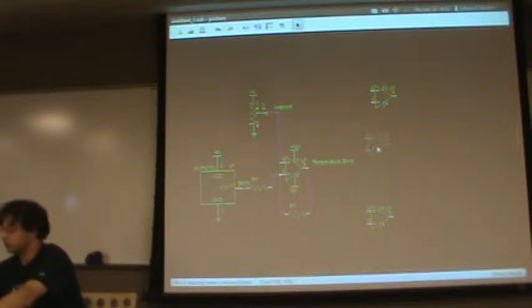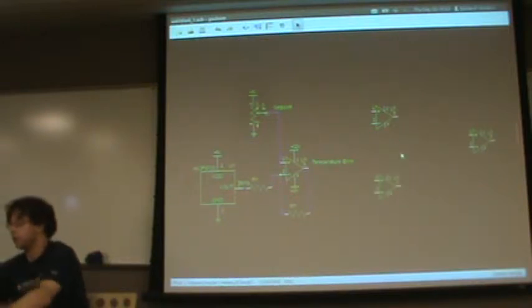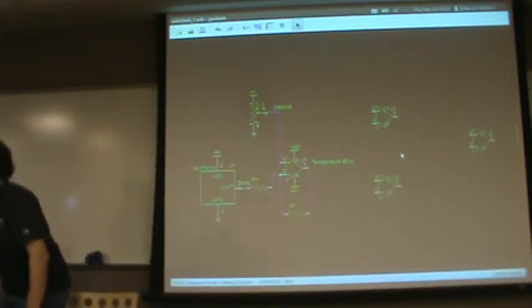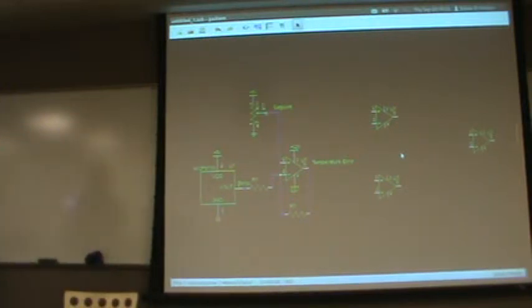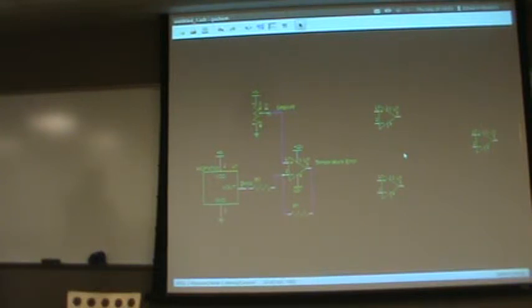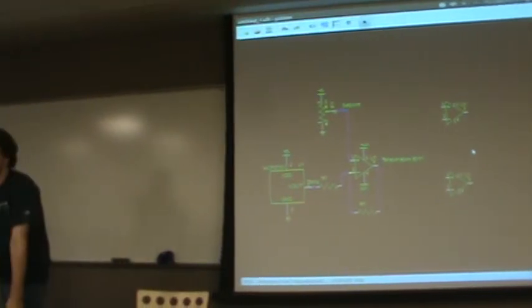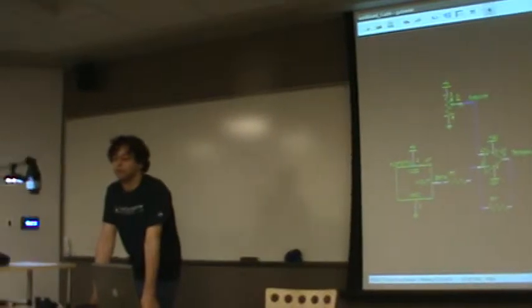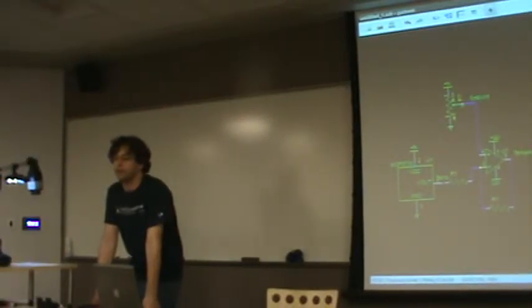So now we've got our temperature error. I'm going to stop very quickly to talk about PI controllers. Basic idea behind a PI controller is you have your error, and if you multiply your error by a big proportional or P gain, then you can use it to control something. So if you have a large error, you would turn on your heater more, and if that's not enough, then you would use a P gain to turn on your heater even more.